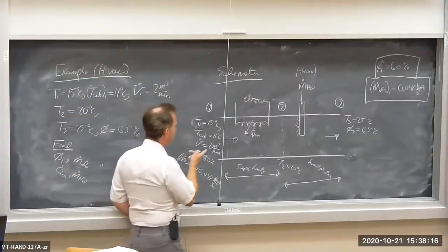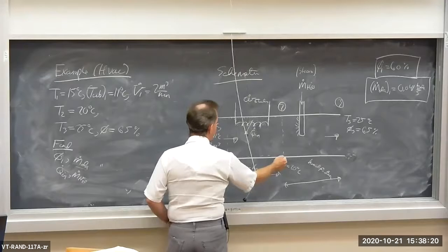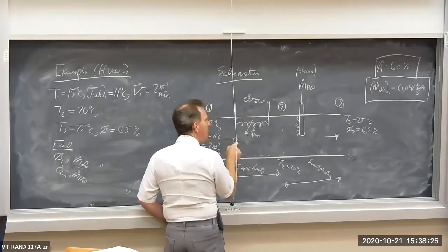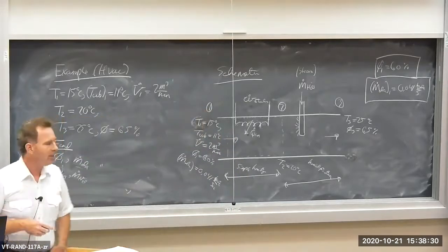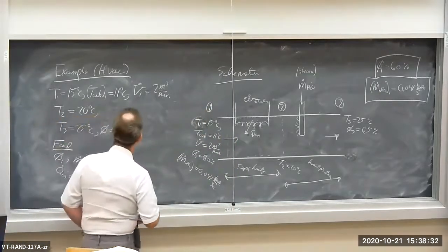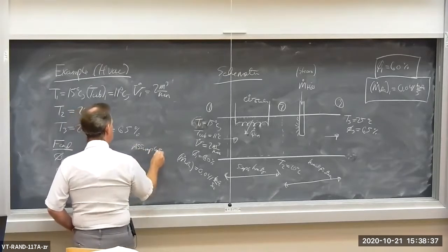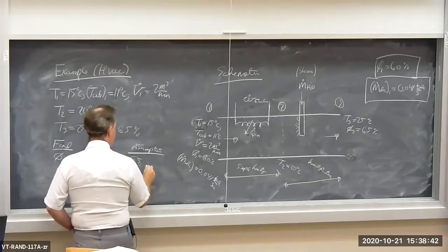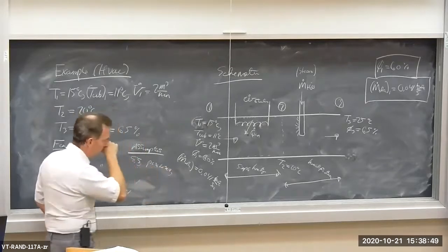Now, we got a heat interaction going on here. We got a single inlet, a single outlet. Inlet is at location 1, outlet is at location 2. No work interaction because I've excluded the wire. It's a heat interaction. Let's assume it's steady state as well. Let's also neglect changes in kinetic and potential energy of the flow. Oh boy, I guess I got some assumptions here. So let's see, steady state. PE and KE terms are 0, so I'm going to neglect those.